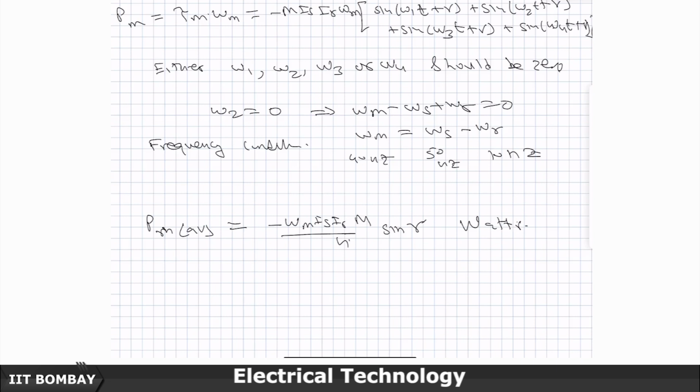So, you create first a two phase motor to start with, by having the voltage of the capacitor exciting one winding and the voltage of the inductor exciting another winding, so that it gets a 90 degree phase shift between the two, and that creates a rotating magnetic field which starts picking up speed. Then the capacitor comes out of the story, and once it picks up some speed, according to the gamma that is set, it can function as a single phase motor.